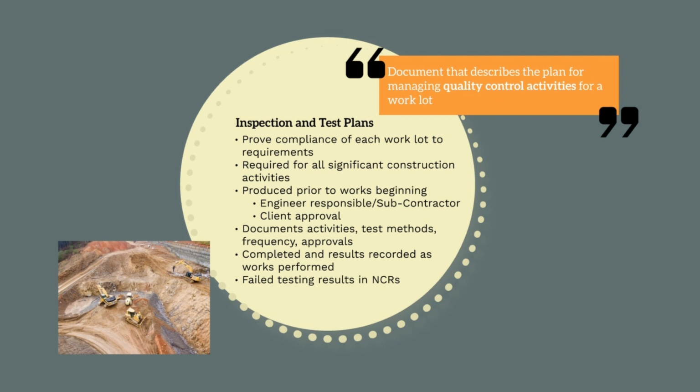The approved ITP will document all the verification and validation activities required, including test methods, documentation to be provided, any hold or witness points requiring sign-off. We'll touch base on these a bit more later. It will also cover frequencies of testing, and who is responsible for signing off and approving the final ITP. ITPs need to be completed as works are performed to ensure no testing or verification points are missed. Any failed tests that can't be rectified easily before works progress will result in an NCR being raised.